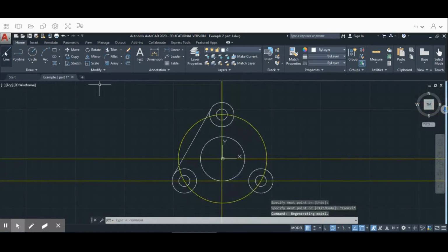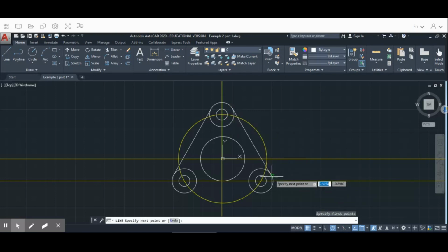Okay. We're going to be selecting that line again. And so now we're going from this side. Okay. So now we're going to go right onto our line, deferred tangent, bring it down here until we're on the line right here, deferred tangent, hit escape.